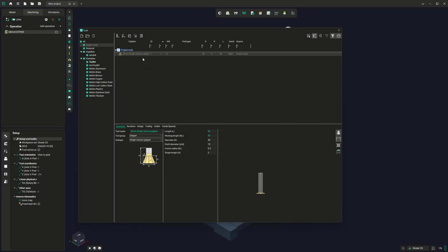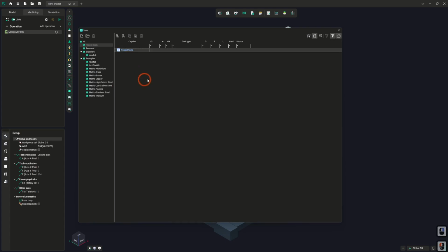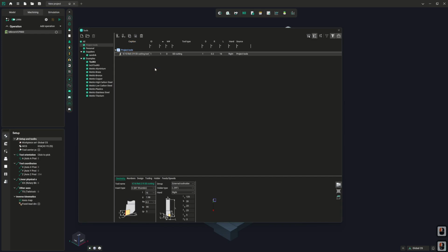So we've now covered the core basics in the milling tooling, so we can delete this tool. And if we take a very quick look at the turning tools, fortunately, due to the world of turning being a little bit more fixedly organized, shall we say, we have got standard insert types listed here. So we are using the predefined ISO standards for insert type definitions here.